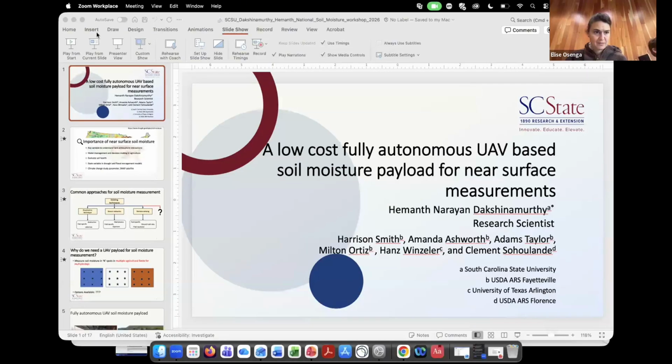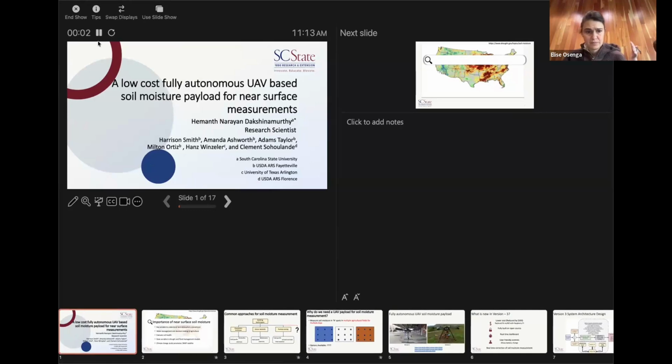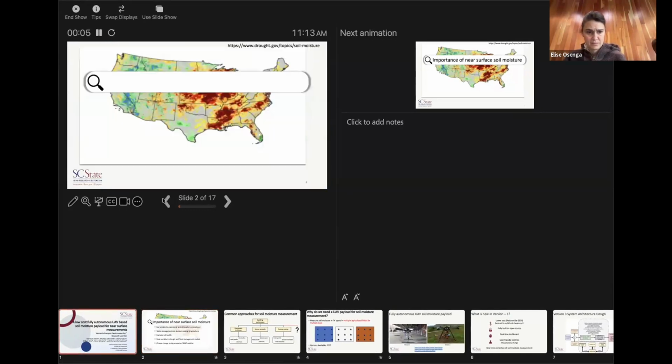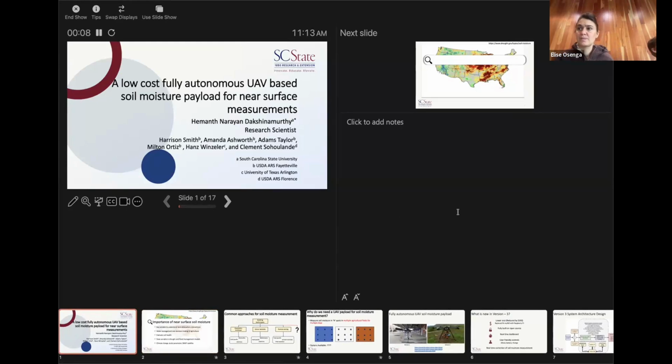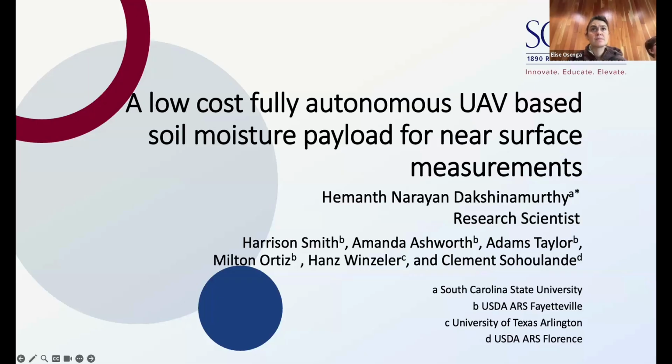So the question was the function is driven by antecedent precipitation, and then there's a fitted loss coefficient. The function itself is like a summation over your antecedent window where what happened yesterday has a lot more weight than what happened before. Evapotranspiration is in there as a theoretical, it's got a sine wave function for day of year. So day of year is a component of that input function. But the pieces of data that you need are the antecedent precip and then that co-located soil moisture and precip to do the calibration on.